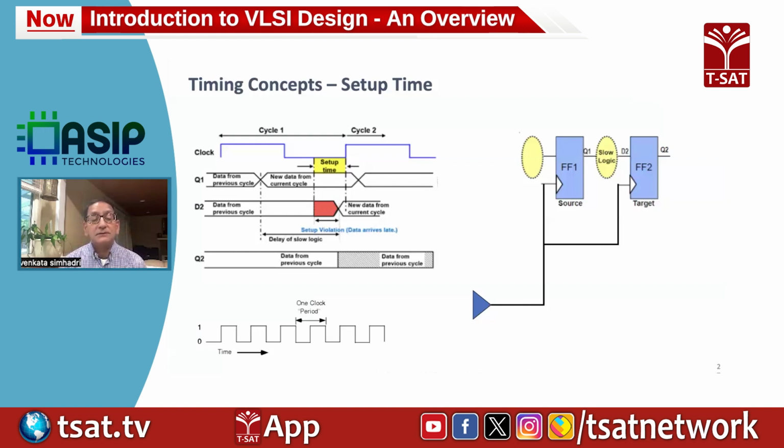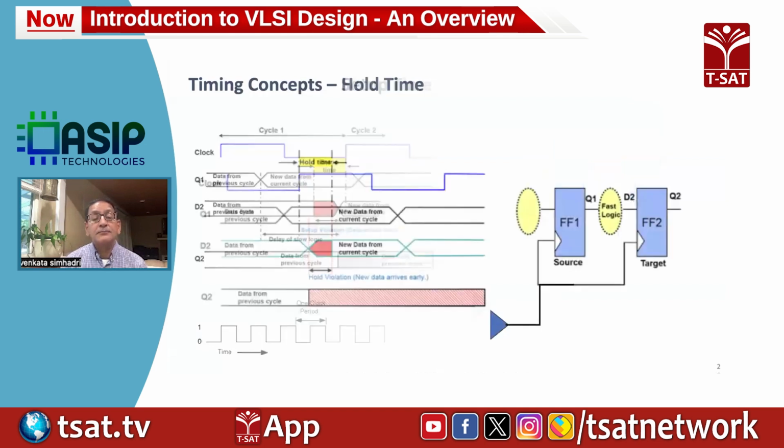So the first thing you need to understand is what is a setup time. Basically, it is the window of time the data needs to be stable before the edge of the clock. So if the data is going from one flop to another flop, it has to be stable for a certain period of time before the clock edge.